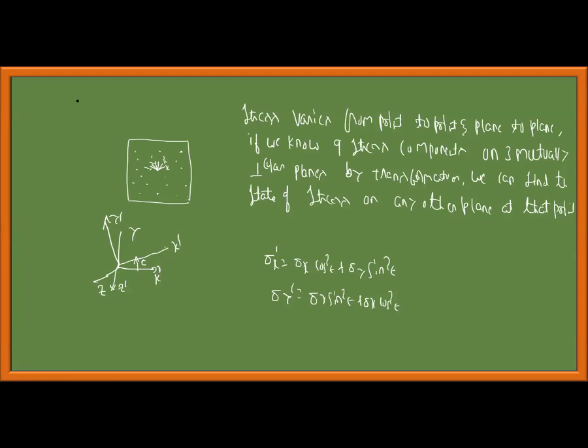But what we discuss for bars, and will discuss for torsion and beams, is that throughout the cross section the stress remains the same. Uniform stress throughout the length of the member. It is not varying. Whereas when you take a tapered bar or tapered cross section, deformation varies. Obviously, the stresses and strain vary, even though we are taking the average there.